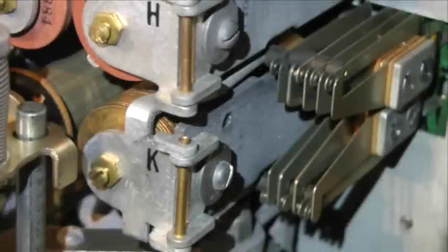For this, a much stronger magnetic field is required, and that is what is provided by the secondary winding. It has more than twice as many turns as the primary winding and receives a slightly higher operating current. With contacts 1 and 2 bottom operated, the energizing path for the secondary winding is closed and the K relay fully operates.